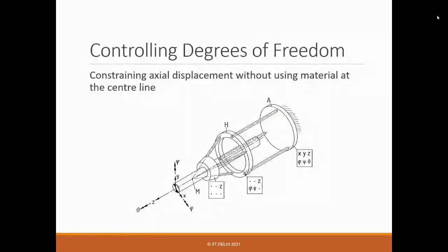And one thing you realize here is that using these principles, using the so-called flexures, in this case you just replace the constraint line with wire flexures. What you can design is something for a very sensitive set of equipment or object which you want to constrain and provide certain degrees of freedom only, but you don't have a place to hold it.